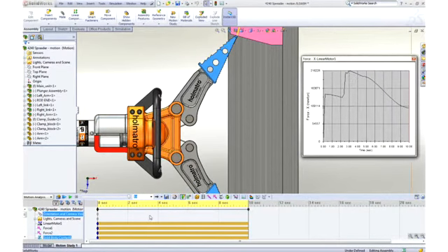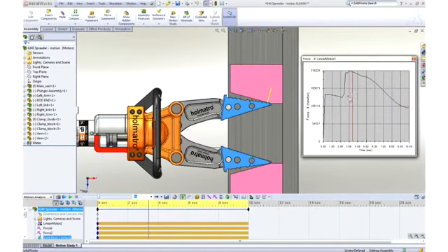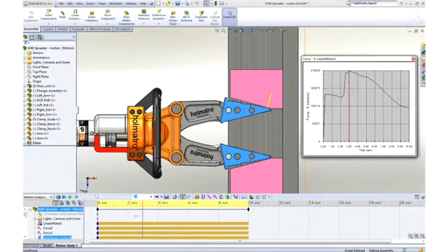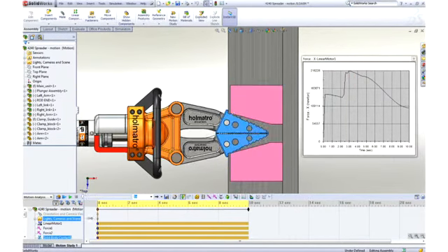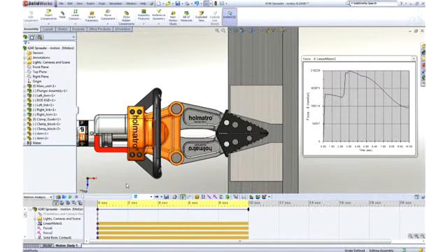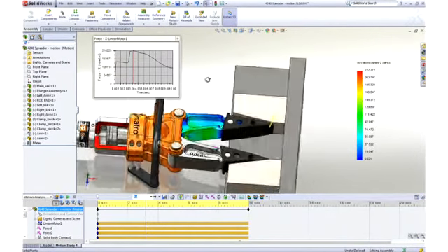We can look at a wealth of engineering data such as the bearing loads on the pins, how quickly parts are traveling, and so on. With the built-in plotting tool, we can quickly show the required piston force with respect to the open position. We're even able to check the strength of selected parts in the mechanism over the entire range of motion. This can really help in determining if we need to use SolidWorks Simulation for a more in-depth analysis to ensure that part strengths meet our goals.